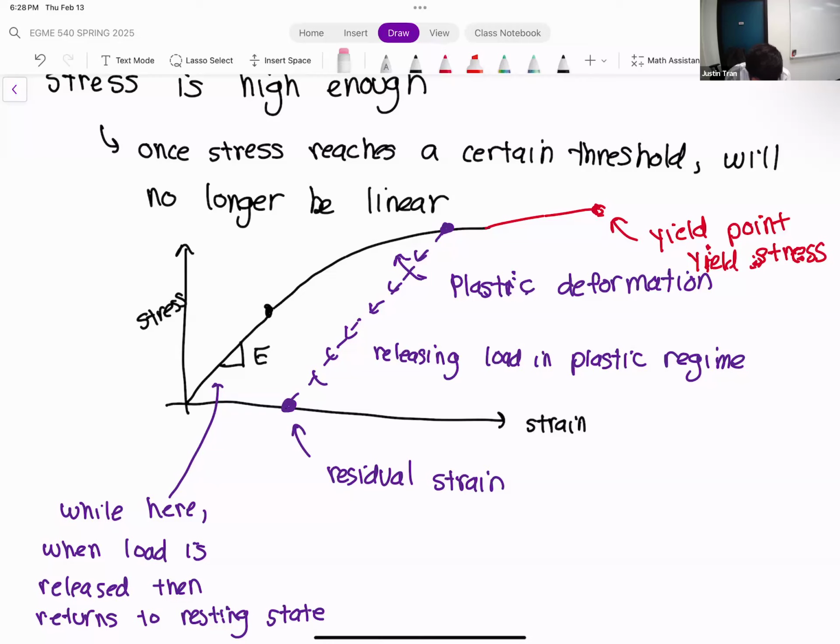If you recall from activity 2, we used a factor of safety, so we didn't carry the stress all the way to the yield point. Well before you reach the yield point, because the yield point is absolute failure, meaning the part completely breaks apart. Usually you're going to have effective failure before that. You're going to be well within the plastic regime.